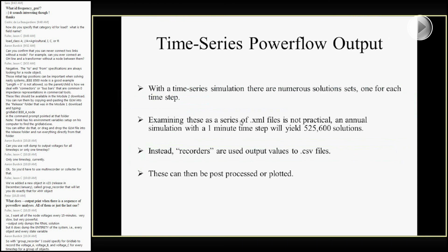So if we want to look at a time series, this is where a lot more of the interesting things come out. The static power flows are useful for, especially if you want to do a peak planning study and you know exactly what your peak load is. But if you want to get more of the time-evolving behavior, and especially a lot of the stuff that GridLab-D is used to do analysis studies for, things like demand response techniques or conservation voltage reduction, things like that, obviously you're going to want a time series out of those.